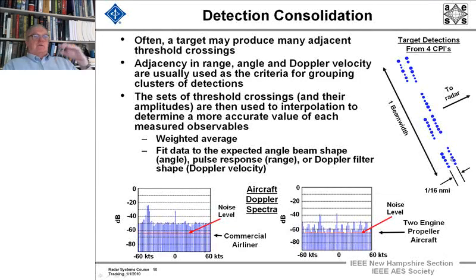One was about 120% of the other, and that was to take care of blind speeds, because this radar is ambiguous in Doppler velocity. So we saw it in this coherent processing interval. In the center, we saw it at both coherent processing intervals, and also in 2 range cells. It was overlapping, and the bigger circle just means it was larger. And here we see it in 2 range cells.